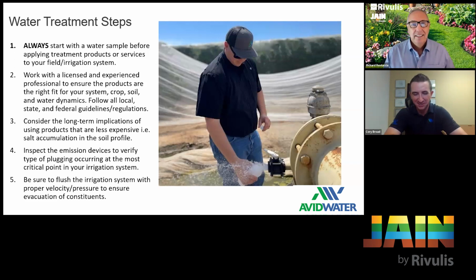So my short answer, with my experience as a micro-irrigation salesperson: absolutely, please flush every day. I think it would be very similar to saying, does changing your oil regularly help extend the life of your engine? My general mechanical knowledge would say yes. Does it mean that your engine will never need to be fixed or overhauled? No. So that last example was probably mostly due to a lack of maintenance on the front end, which led to a whole lot of maintenance and chemistry on the back end. And so I would say that regular and proper flushing will always help.